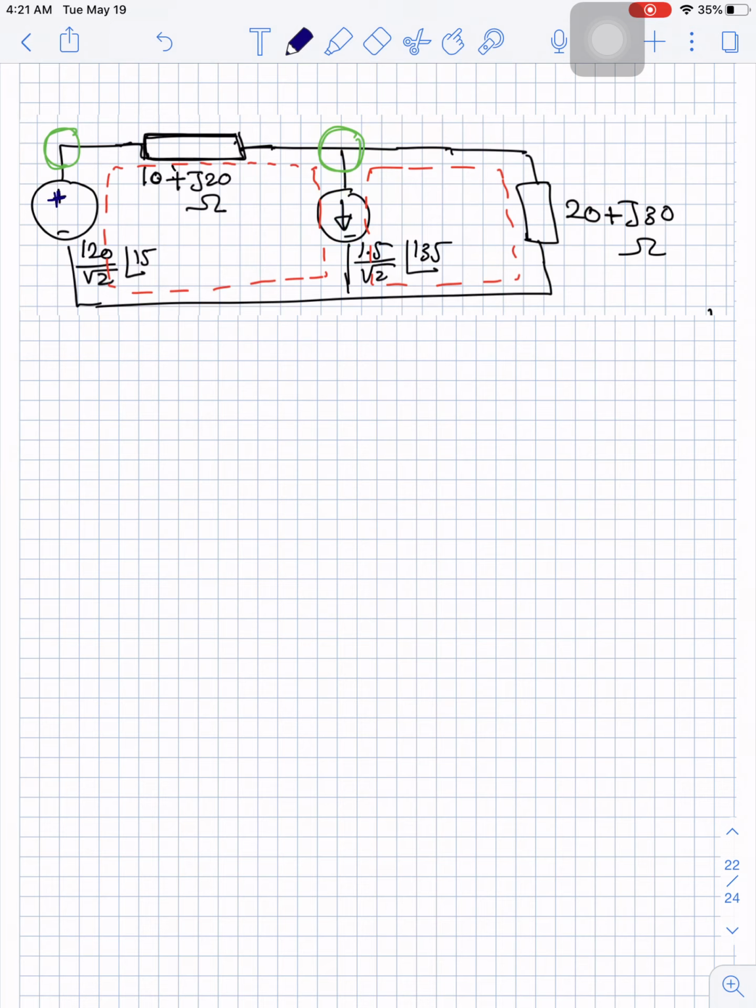So here we have a voltage source. This voltage source will have current going out of it. The current will be leaving the positive terminal because it's a source. And we can name this current as I source. And the current going from the source is the same current here. It's like we applied KCL at this node. So we said that we will assume the current, and while we are assuming currents, we will do KCL. So the current I source will enter this impedance, so the current here is I source.